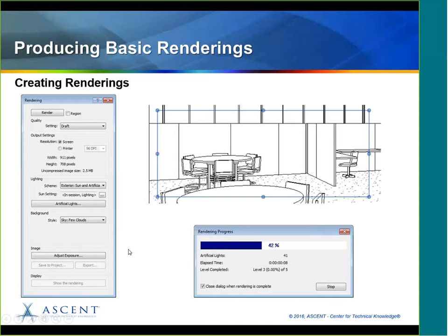So in this section, just because of our time, all I want to do is really go through a few things in the rendering dialog box. And of course, you need to be in a view that you can render, and then you can set up your rendering, and I'll go through each of these. One thing to remember is to start with the lowest amount of rendering that you can see enough, and also render a region, and that's what you're seeing over here.